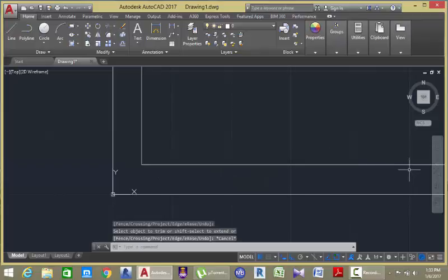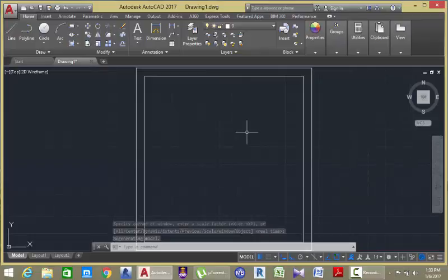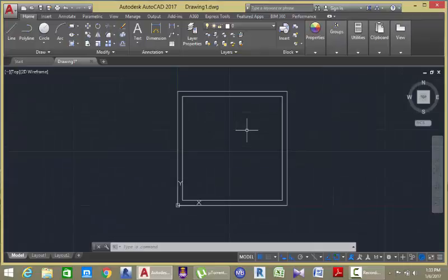Go to the navigation bar and click the Zoom Extents button. We need to see the bottom area of our drawing, so zoom out a little bit by rolling the mouse wheel backward towards you. Then go to the Home tab, Draw panel, and select the Line command. AutoCAD asks you to specify the starting point of the line.